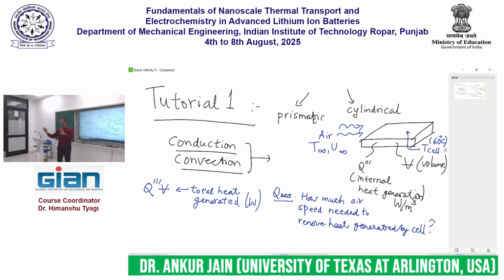So this cell is at some temperature T cell which is around 60 degrees C. If it goes beyond 60 degrees Celsius, we are entering dangerous territory where a lot of bad things can happen. What bad things we will learn tomorrow. For now, let's just say that I want to design the system in such a way that the temperature of the cell does not exceed 60 degrees Celsius. Whereas the air that I have at T infinity, what's a reasonable value for T infinity? Sure, let's say 20 degrees Celsius.